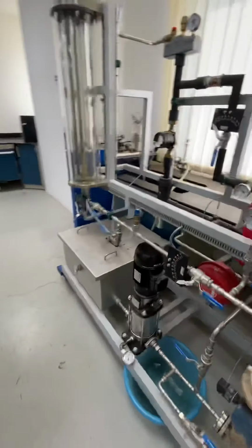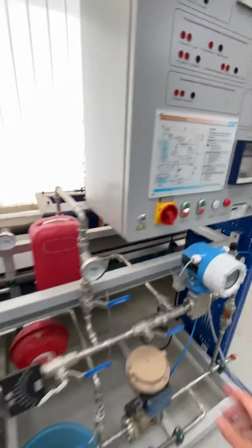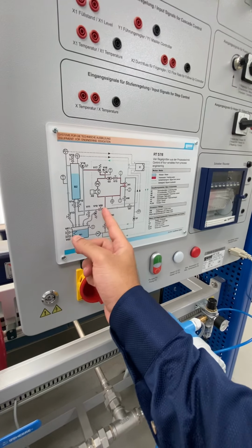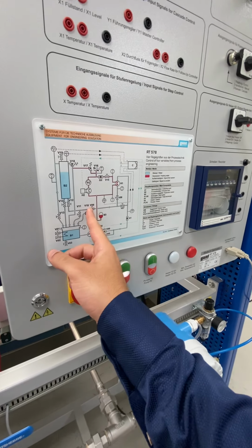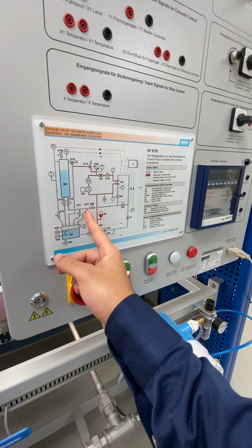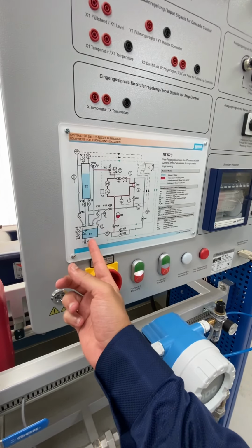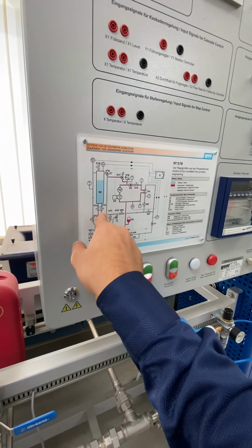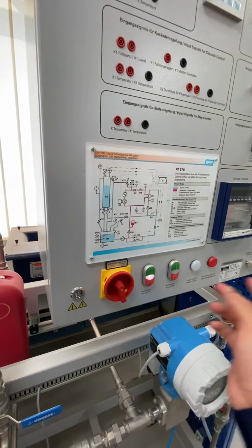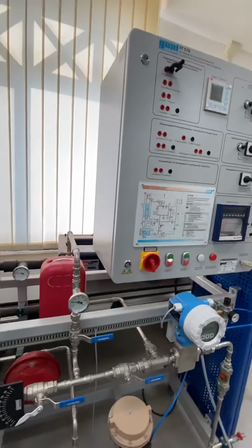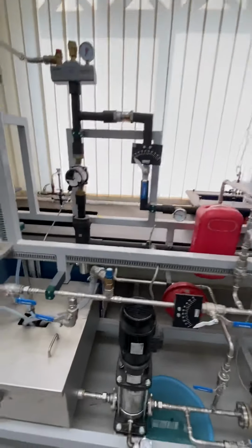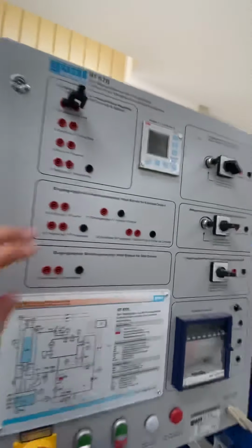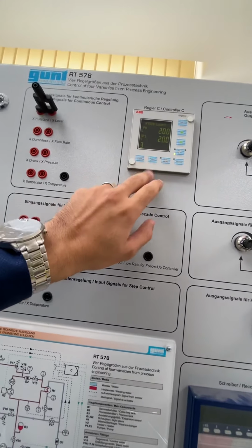So what's going to happen in this situation is that if this valve V10 is open and gets stuck open, the flow will start from V10 and go through V10 back again to this collecting tank B1. So that causes the inlet flow rate to tank B2 to drop, and as a result of that, you will see that the output signal will start to increase. Okay, so let me show you. I will try to simulate this scenario.